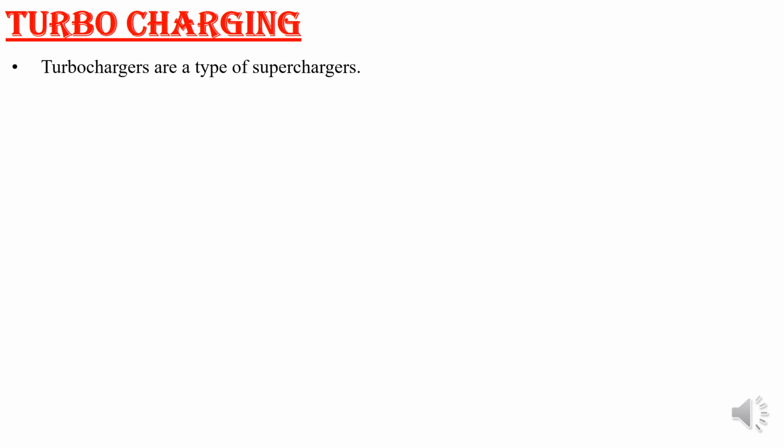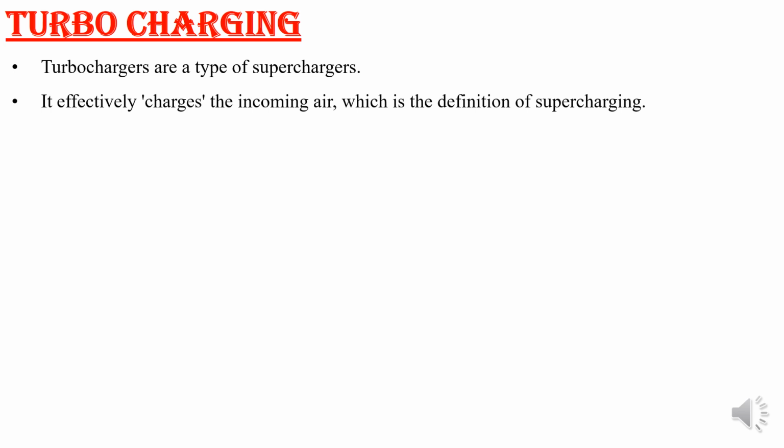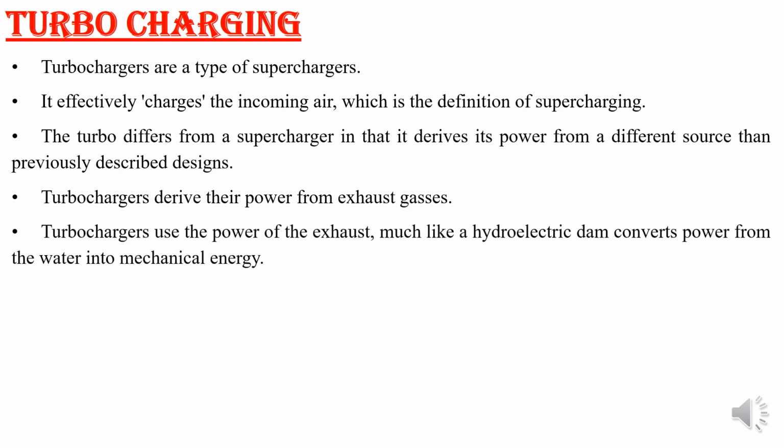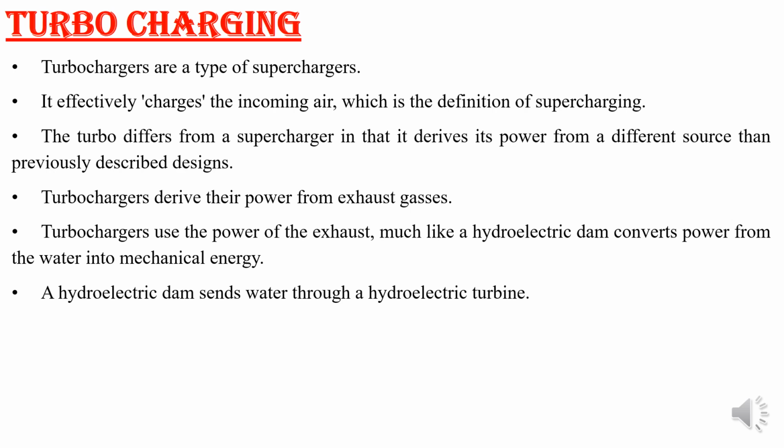Turbocharging. Turbochargers, as already mentioned, are a type of supercharger only. That is the second method. It effectively charges the incoming air, which is the definition of supercharging, that is, it increases the density of air. So the same principle as the supercharger is there, but what is the power requirement for that device? It is taken from the exhaust. That is the only difference.